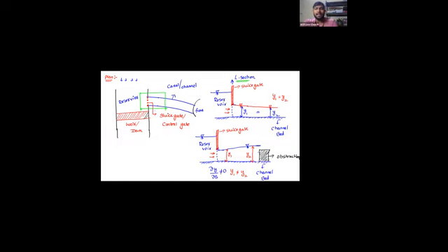What is steady, unsteady? I don't want you to mug up the definitions. I want you to understand what is actually happening. If there is no obstruction, the water has the same flow. But when I kept the obstruction, what happened? Once the water meets the obstruction, the energy levels change and the water level is going to be disturbed, right? The entire upstream water surface is disturbed, so the depths are not going to be the same. Yes or no? So this is the unsteady flow.